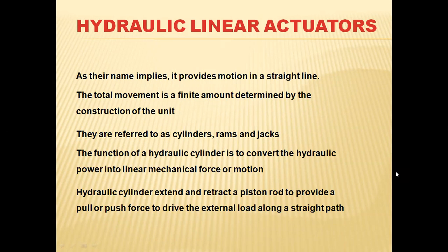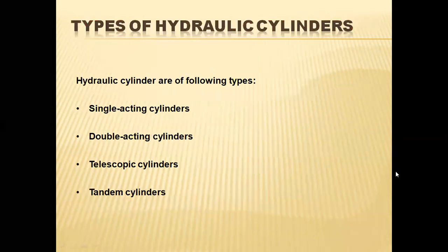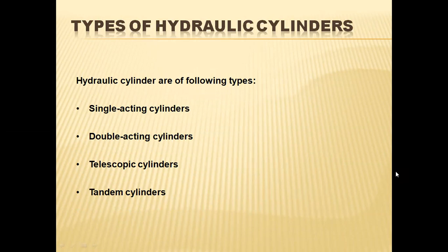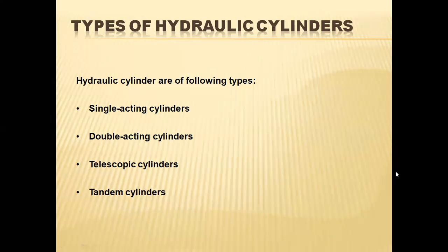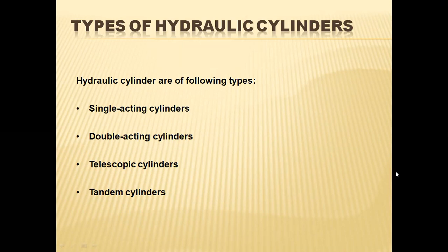As the fluid enters input port 1, output port number 2 returns the already entered fluid back to the reservoir, as we have seen in yesterday's class. And vice versa, the directional control valve specifies the reverse motion, that is, entry of the pressurized fluid towards channel number 2 leads to reverse flow at port number 1. From port number 1, the fluid that entered when the forward stroke took place is drained back to the reservoir again.